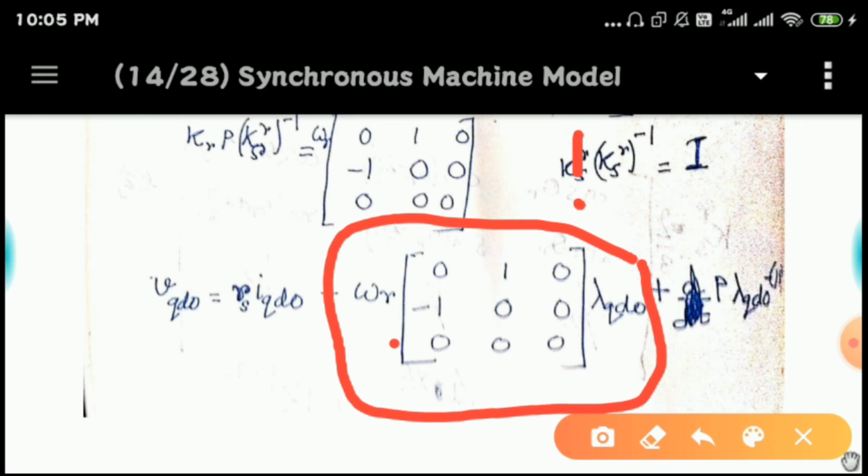Even for a very high speed rotating disc, if you ask someone to stand at the center point, then he or she will not be able to realize any rotational speed of that disc. The same thing happens for the third harmonic case, and that is why the third harmonic voltage does not get any contribution due to the speed of the rotating reference frame, and it is always zero irrespective of the speed of your rotating reference frame.